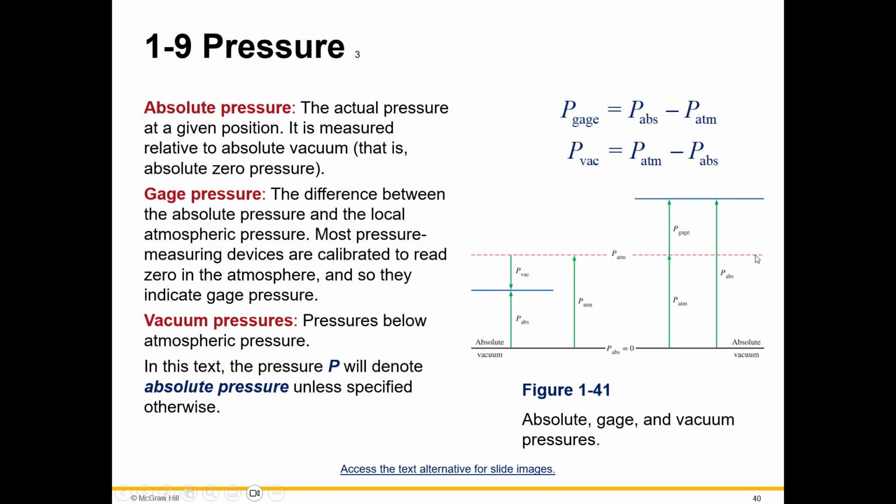And then look over here for your gauge. Okay, so you've got your atmospheric pressure still here. You've got your absolute pressure, which is way higher, and the difference between those two is your gauge pressure. So the formulas work just fine, and you can write down the definitions, and those are important. It's important to know what it is and those assumptions. But in my opinion, the schematics and drawing these are the most helpful because it helps you visualize how they work together.